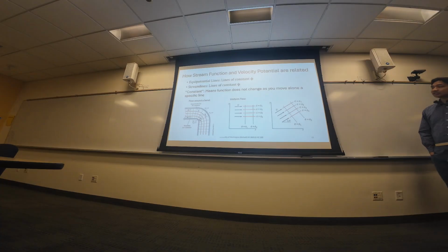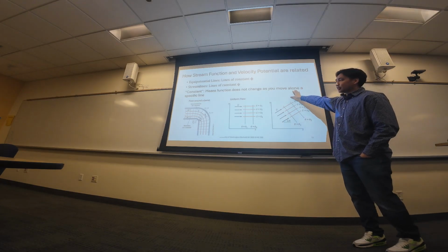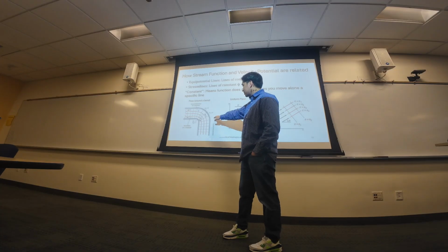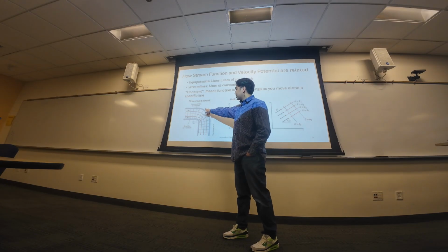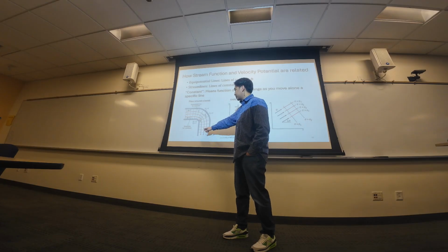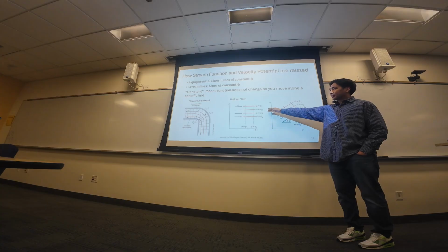And here you'll see some more figures of how that works. These points are the same. So flow around a bend here: you'll see your velocity coming this way. And then your equipotential lines are perpendicular. Equipotential just means your phi function is constant. And your psi, these are your streamlines. They're perpendicular. Same here, uniform flow.